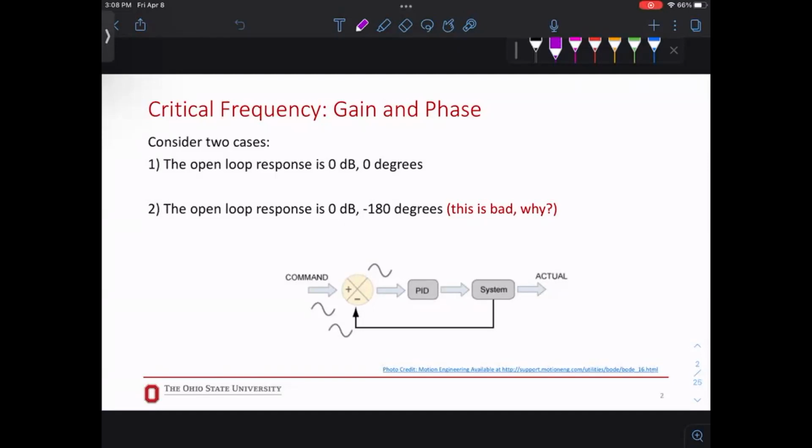So if you think about an open loop response, where you don't have the feedback coming in, the system does not see the feedback. If you send a sine wave, and this sine wave has a 0-degree phase shift at the output, you send an input, you get an output. Now, if you wanted to look back at it and see the difference, since the phases are the same, or they have a 0-degree phase difference between input and output, the error you get is the actual error of the system, right? Now, if there was a phase shift of 180 degrees between your input and output,